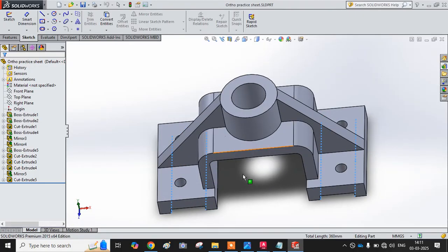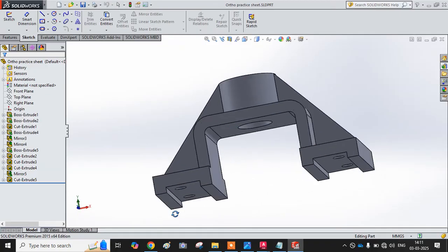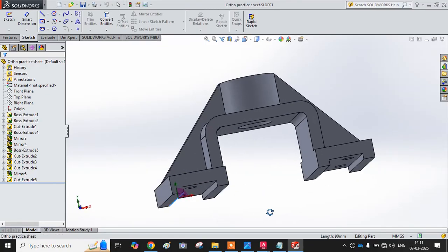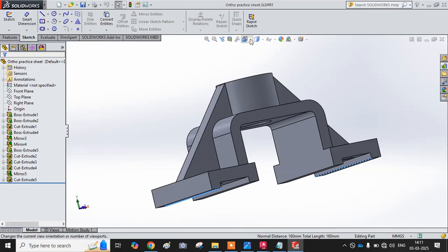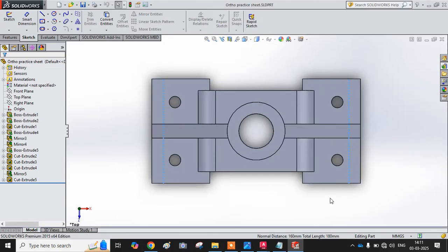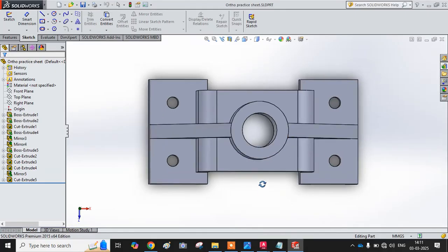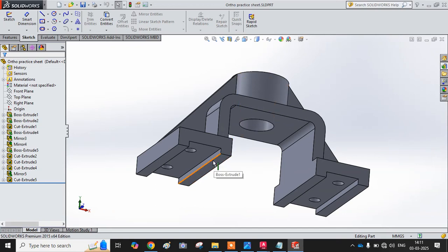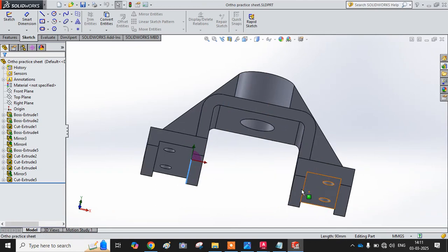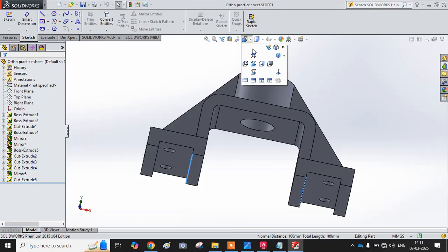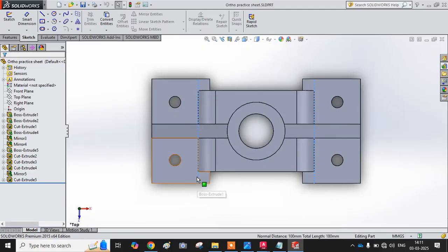तो देखो, अगर मैं ये outer edge select कर रहा हूँ ना, this edge and this edge, if I select, you can see in the top view, it is throughout hidden. Inside the rib also it will be there. Okay, इधर से rib के बीच में से भी जा रहा है hidden. But if I select this edge and this edge, there is very complex drawing. First it is hidden, then it is dark, then again hidden, then again dark, then again hidden, like that. Is it clear? In this way you have to draw the front view and top view.